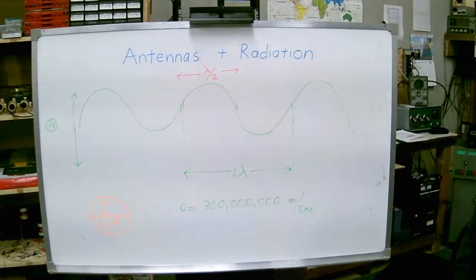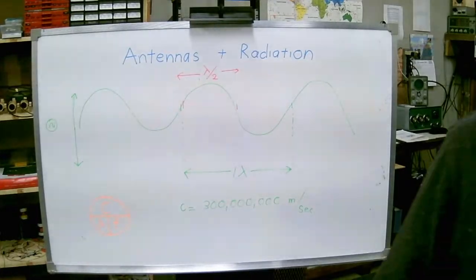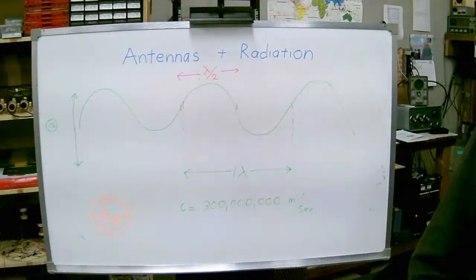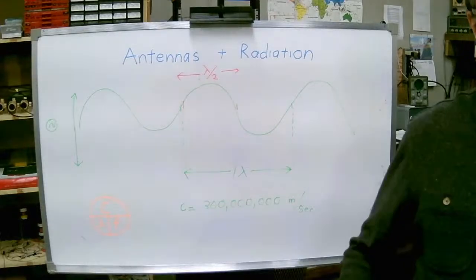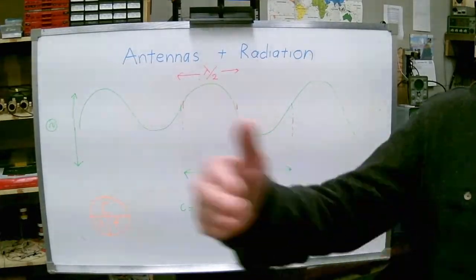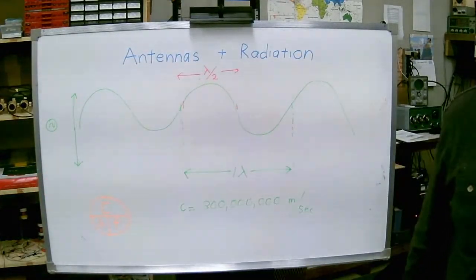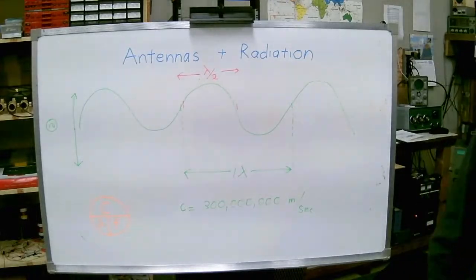So a piece of wire, for example, would have a distributed, infinite number of infinitesimal inductors in series. So we can no longer say this is an inductor here. We've stretched this inductor out over a long distance. Same with capacitance.